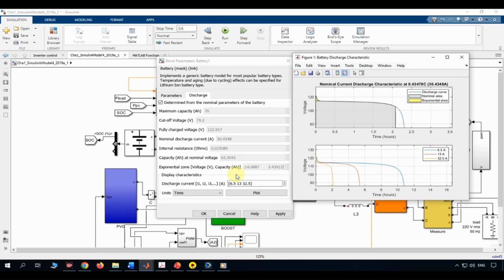And critically, this is the exact same battery whose state of charge feeds into the energy management system we covered in the last video. The SOC number driving all those charge/discharge decisions is being computed live from this discharge model, current in, current out every simulation step.